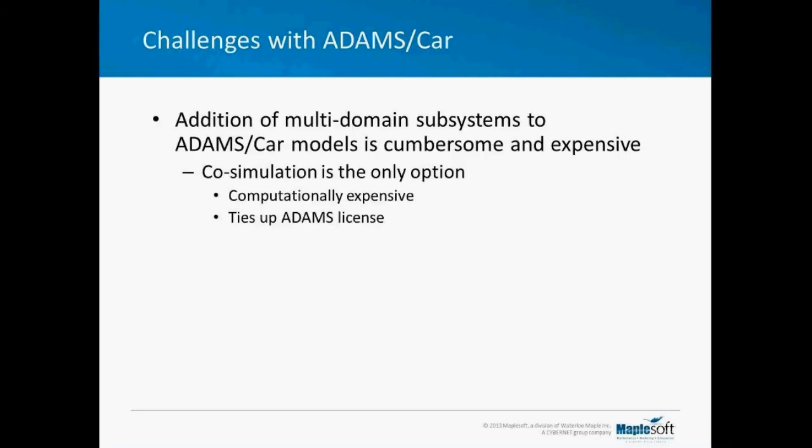Clearly, with Adams Car, it's a major challenge to add further multi-domain subsystems into that environment, and we've heard many times that it is cumbersome and expensive to do that. The only option you have is to use co-simulation, which is computationally expensive and ties up an Adams license where you may not actually need to do anything more in the Adams environment.